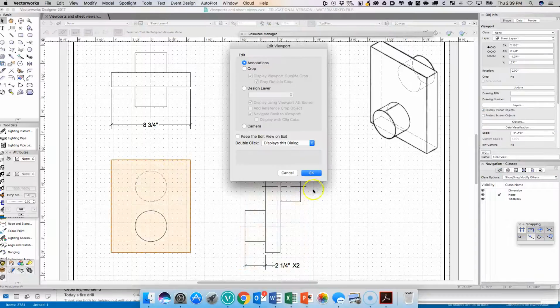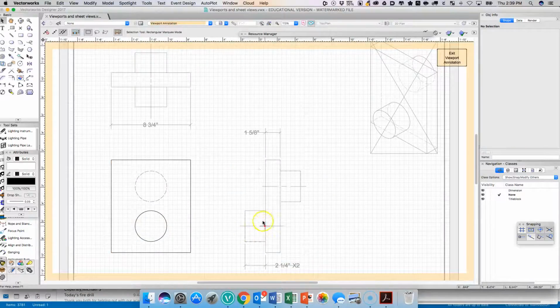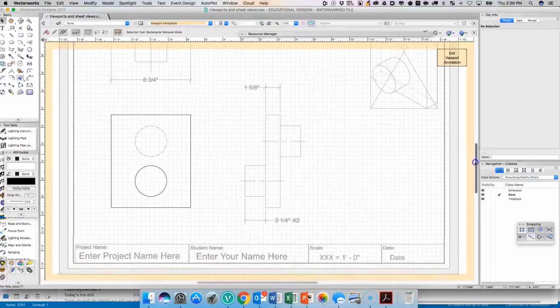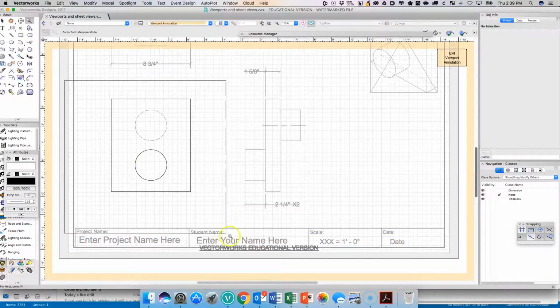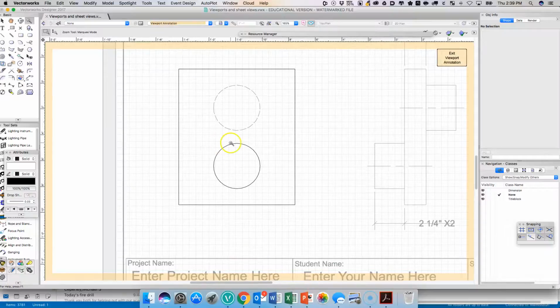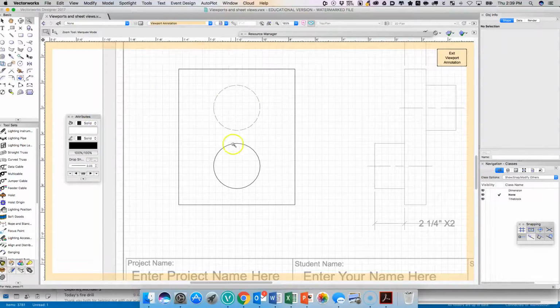And there's a little more going on here, and there's a little trick we're going to have to learn to use this. So I'm going to zoom in, and we'll quick dimension, do our linear dimensions. So our first, well, we need to put in the center marks for the circles. So if we want to center mark circles, I'm going to come over here to our dimensioning tool set, look down, and here's our center mark.